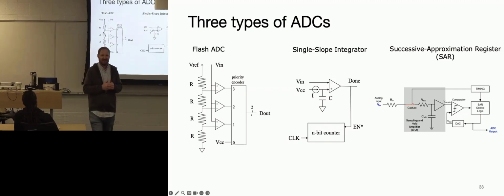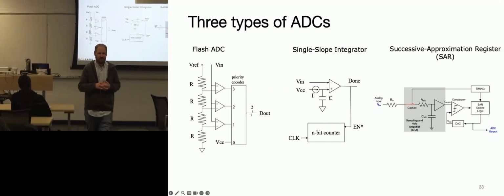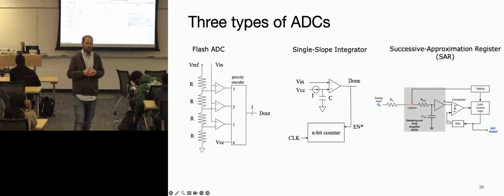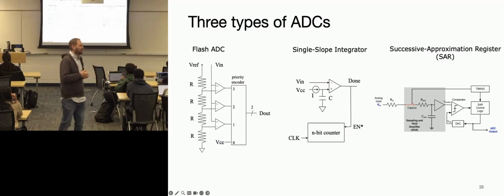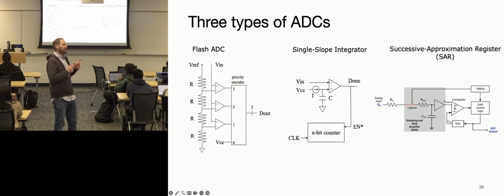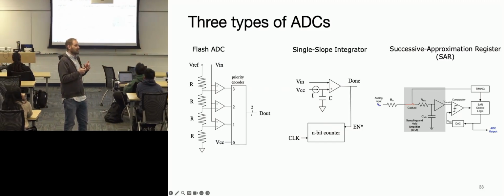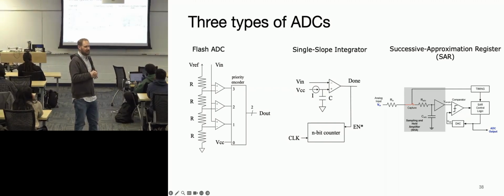The single slope integrator, do you typically have control over both the speed of the ramp and the clock frequency individually, or does one? Just one. Okay. Rarely do you see slope integrators that are configurable as an integrated part of something like an STM32. It's usually an external module. There are some microcontrollers that have them, but they're really good for little handheld consumer product devices that are trying to measure something in analog.